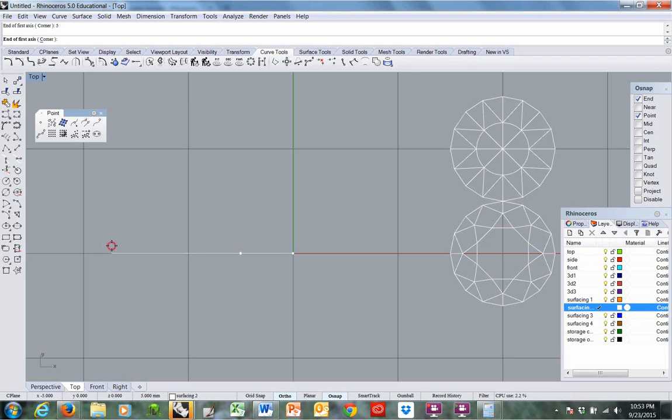So I'll left click. It wants the end of the second axis. I want that to be 12, so half of that, the radius of that is 6. I won't need to hold down the shift key anymore. Once I type in 6 and enter, it'll complete the oval. Not quite, I have to still click because apparently it believes I could go in a separate direction. I really can't. So anyway, pull up and click. And there you have your ellipse.